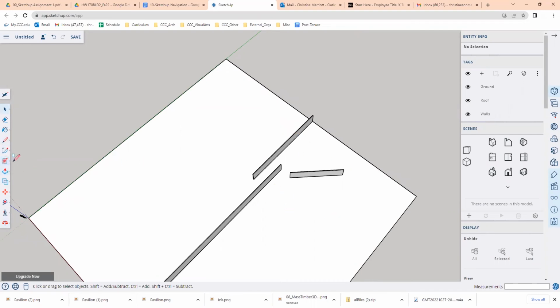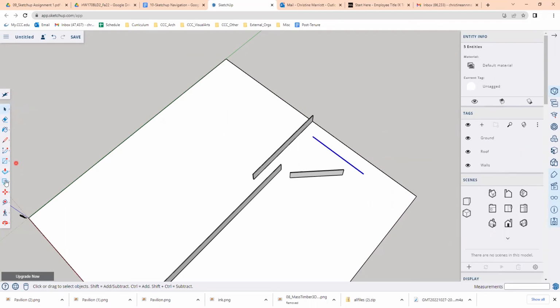So let's go ahead and create another rectangle. Try to make it roughly in relationship to that wall there. This one, let's see here. I may have to complete this one a couple of times. For now, I'm going to put 50 feet, 5 inches. Good. I'll use the selection tool to capture them all.